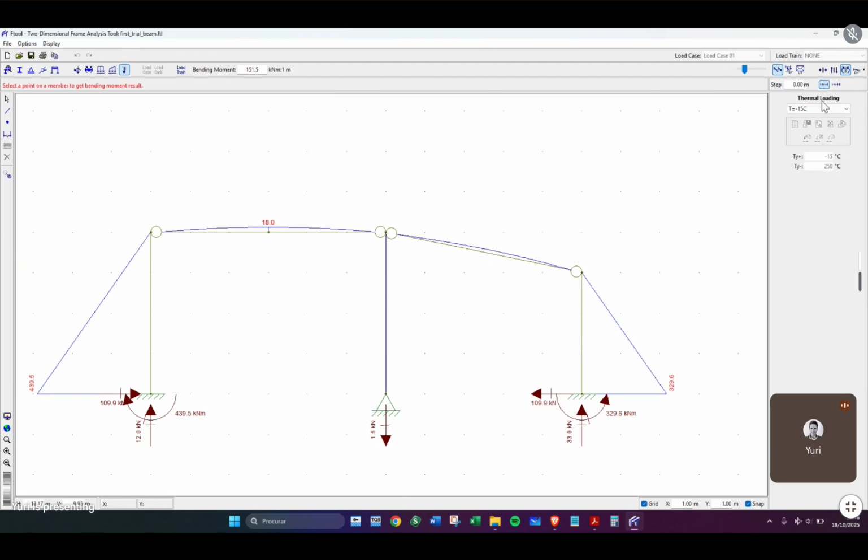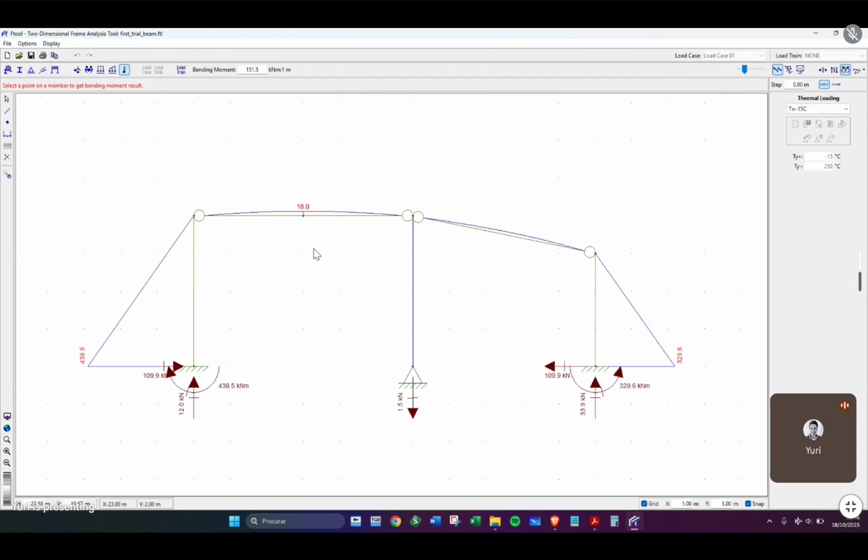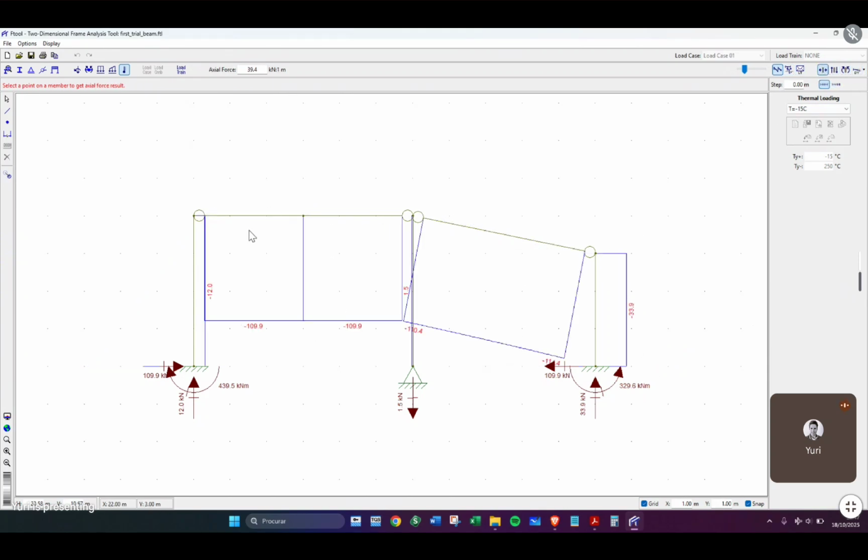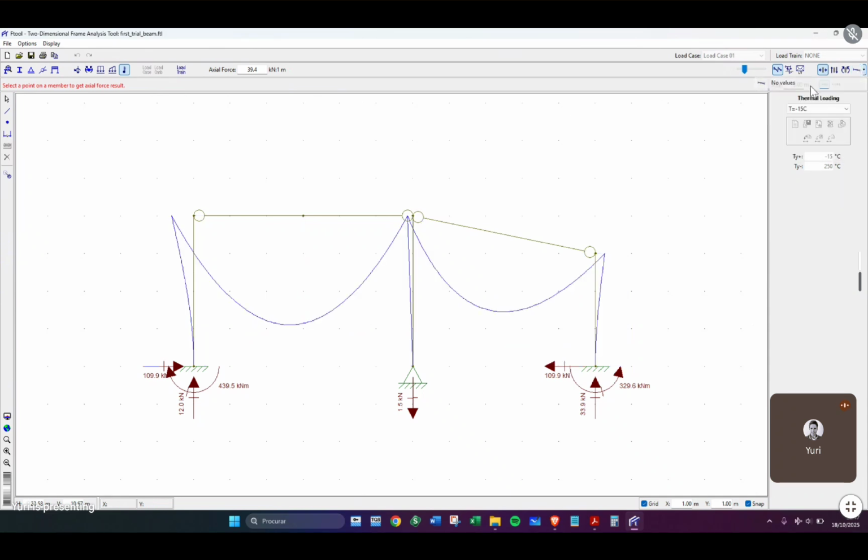Okay, a lot of different results. So as you can see here, the flexural moments in the columns were excessive, all right? So the fire within the structure actually changed a lot the internal stresses. Let's see bending. Oh, look how much compression load this is. And let's see the deformation as well. Deformation was quite significant here too. Oh, 50 millimeters. All right.